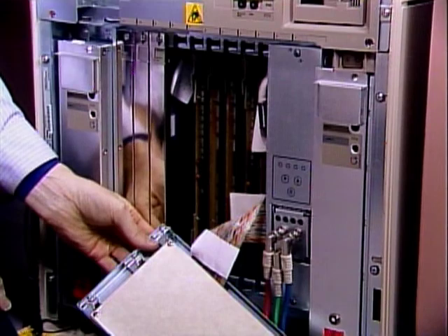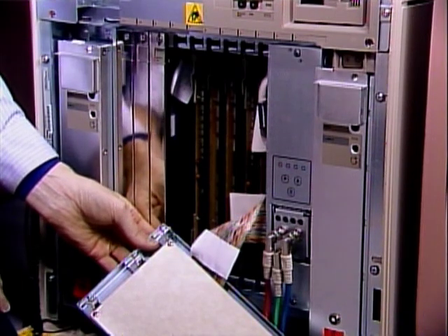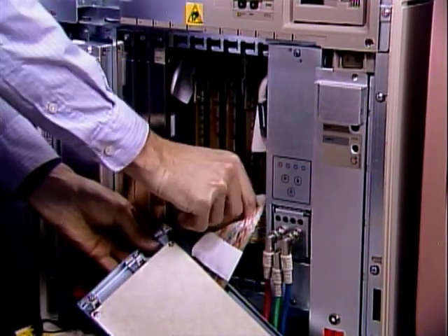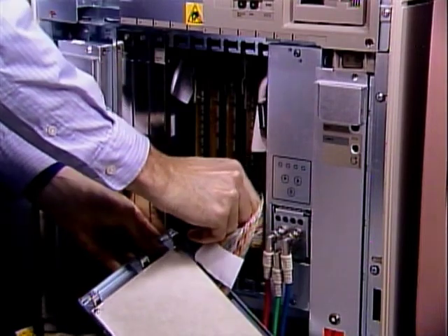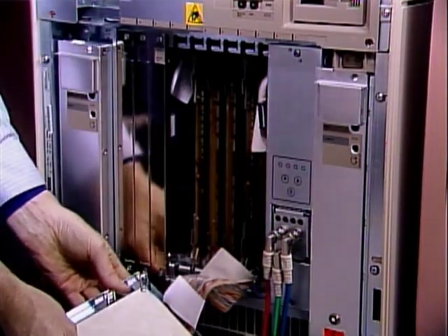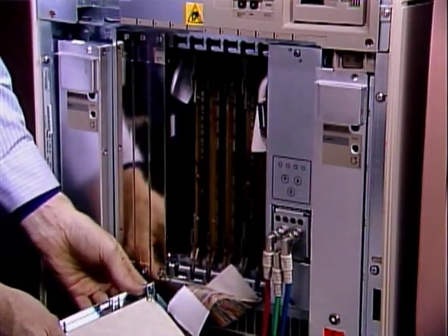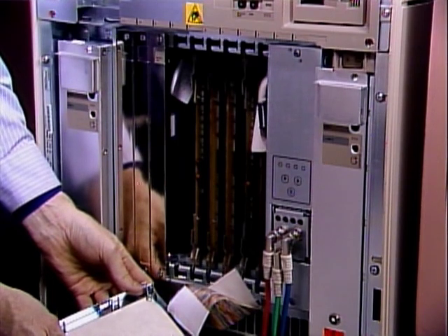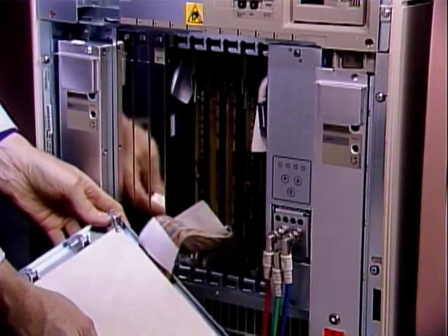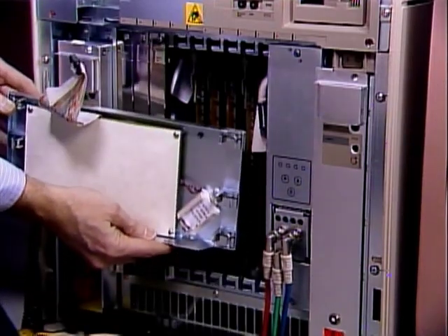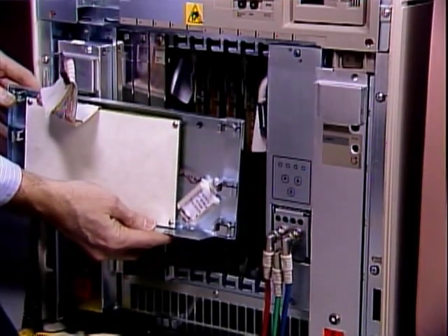Before you remove a module, you may wish to disconnect the ribbon cable from the I/O module. Removal of the cable is only necessary if you are removing the I/O module. You will probably find that it is more convenient to work on the system with the cover module out of the way. However, removal of this cable also disconnects the battery from the BBU-ROM, and the information that had been previously stored will be lost.